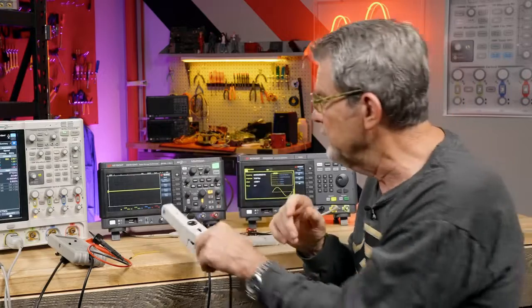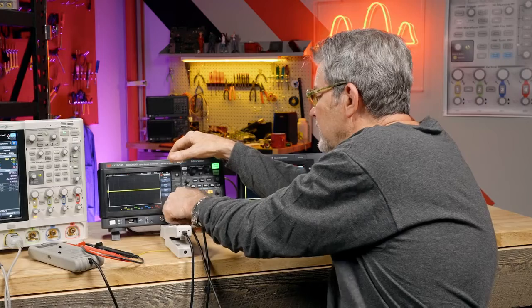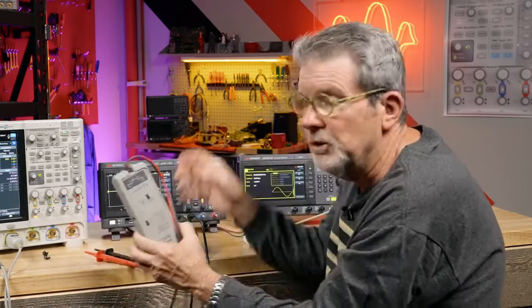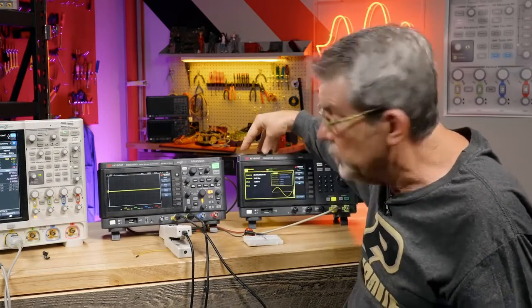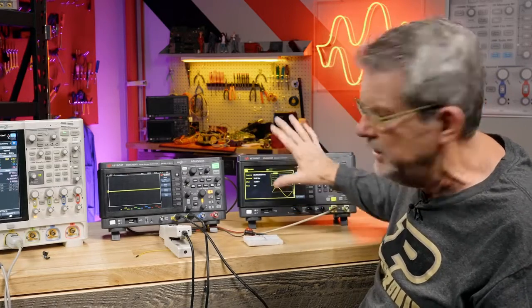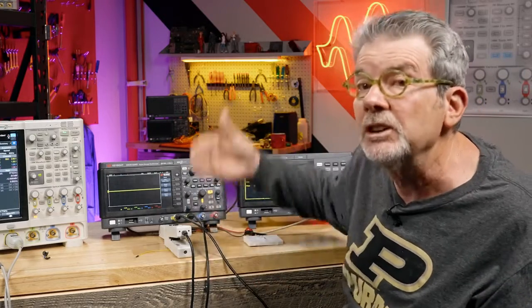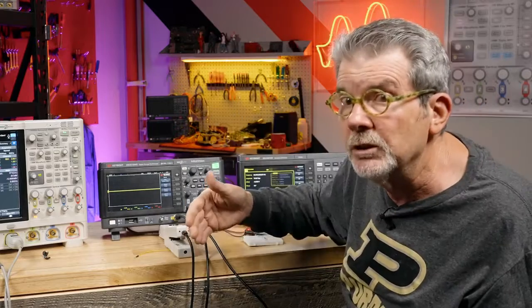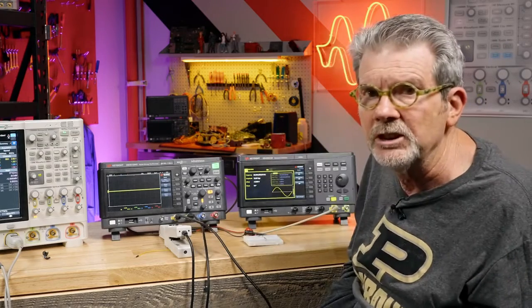Let's go ahead and turn it on. And let's also connect up our high voltage probe and turn this one on. And what we're going to measure is the input AC voltage to this function generator. Has nothing to do with what the generator is generating. Just think of this as any system or any DUT. And we're going to measure the input voltage and the input current. And ultimately, in the lesson after this, we're going to measure the power consumption of this particular instrument here.